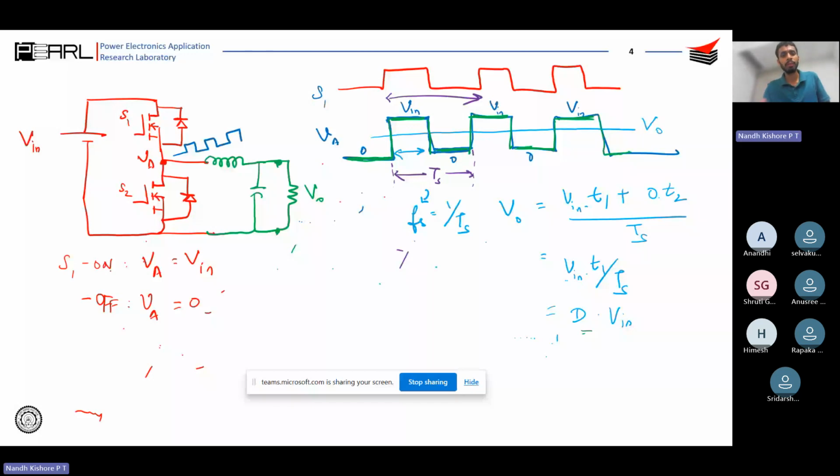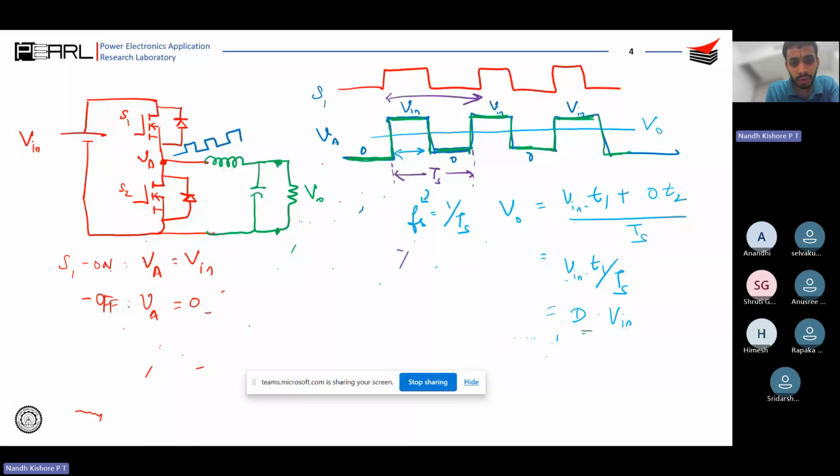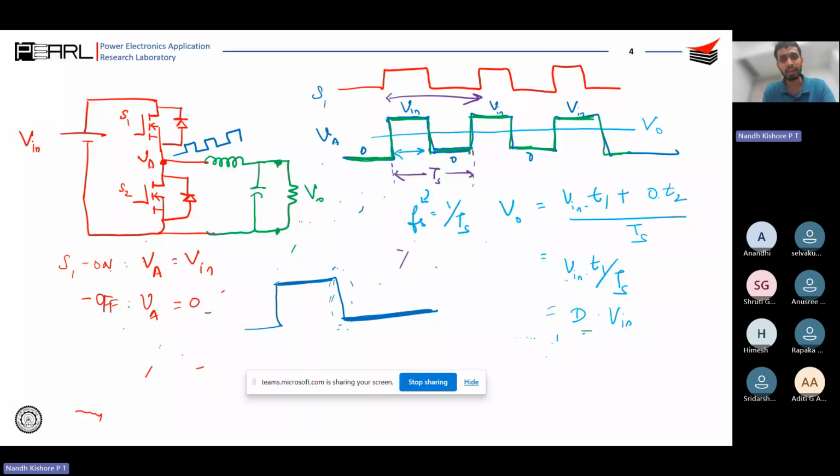And it makes sense also. So from whatever we have drawn so far, let's say I take one cycle. We understand that this time interval is quite large, but probably the transition happens in a very small time, so we are not concerned about it that much. It doesn't affect my converter operation in any manner, so I need not worry about it. That's the reason probably we consider that S1 is on and S1 is off, correct? We never consider what happens during these transitions, right?